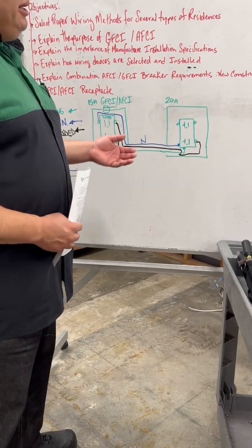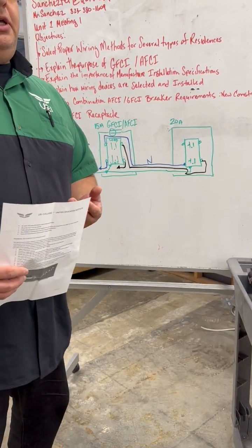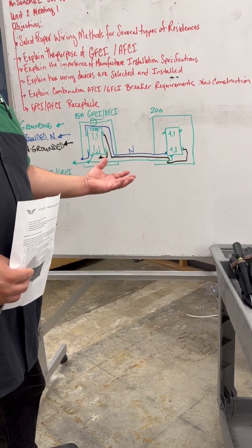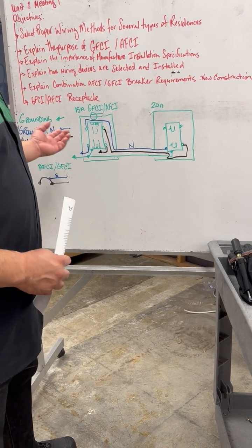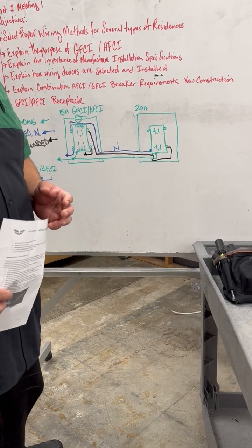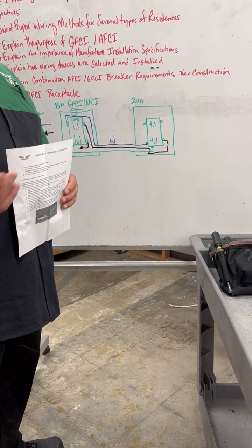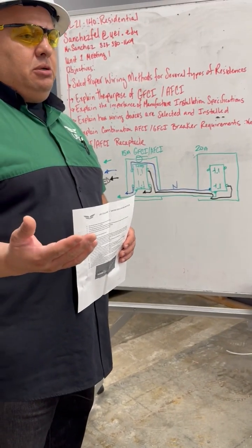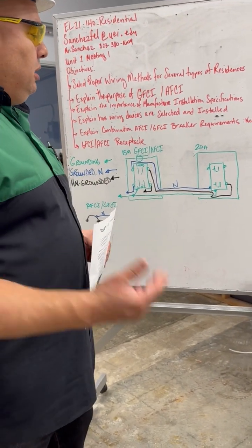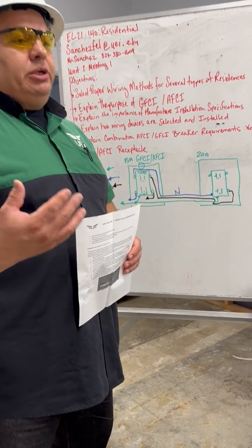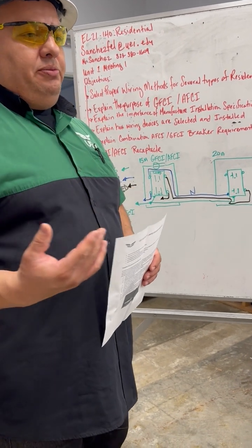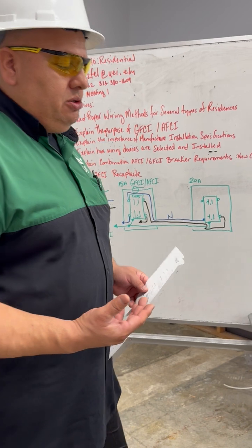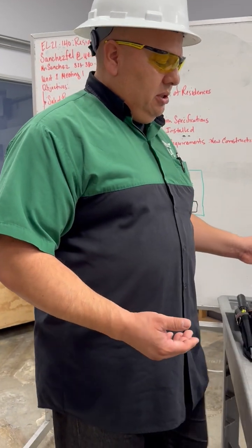So just keep that in mind, always incorporate the NEC in the materials. What does the NEC say about the materials I'm using today? What does the NEC say about the requirements of AFCI, GFCI? And like in California, again, we want to make sure that we're following all the standard codes like the California Electrical Code, Title 24, and seeing if there are any more restrictive codes that we are aware of, whether it be an AHJ jurisdiction that we worked in and so forth. We want to bring those points.